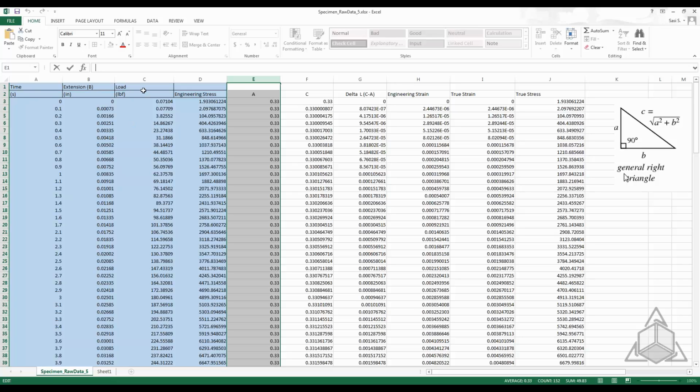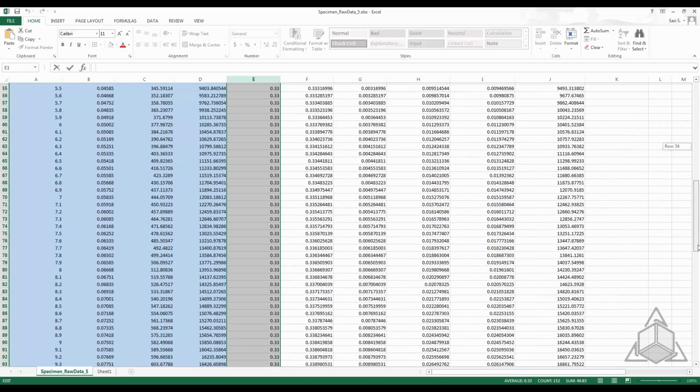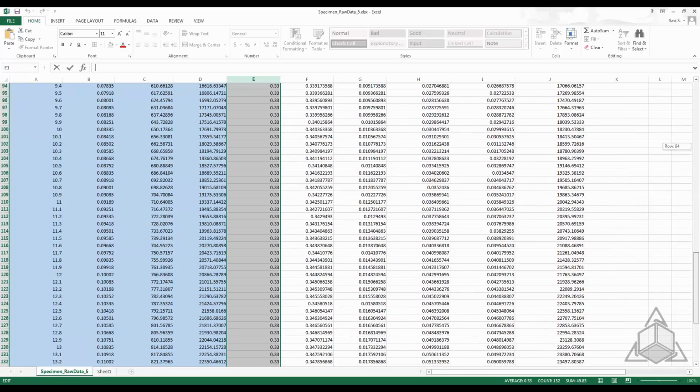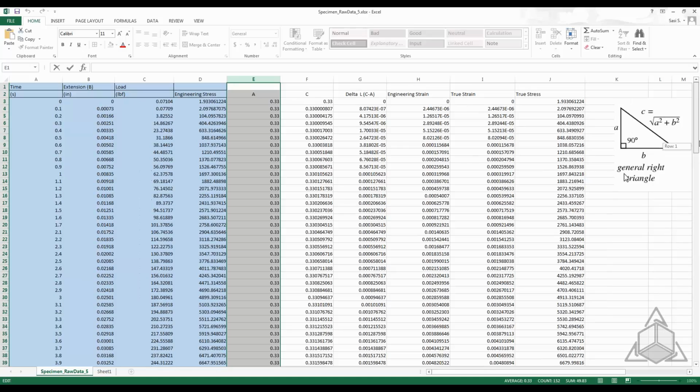Of course, the load will also be applied. We are trying to work our way up to 400 pounds. You will see that over 15 seconds, the load accumulates to, in this case, much higher than 400 pounds. The reason I did not use 400 pounds in our linear stress analysis is because the part essentially buckled. That would be a really good showing that linear stress analysis might not be a good type of analysis for that test.